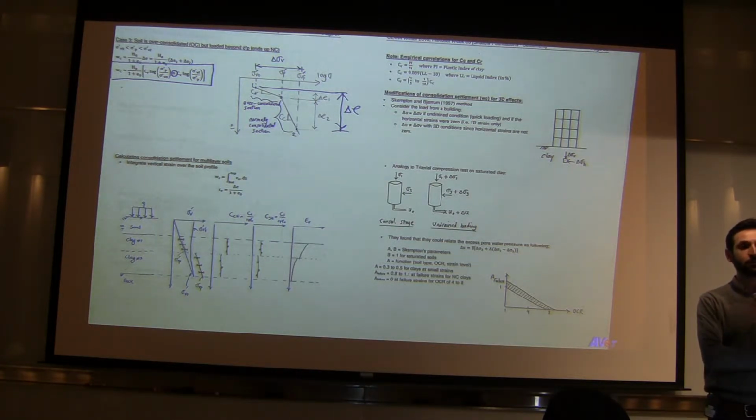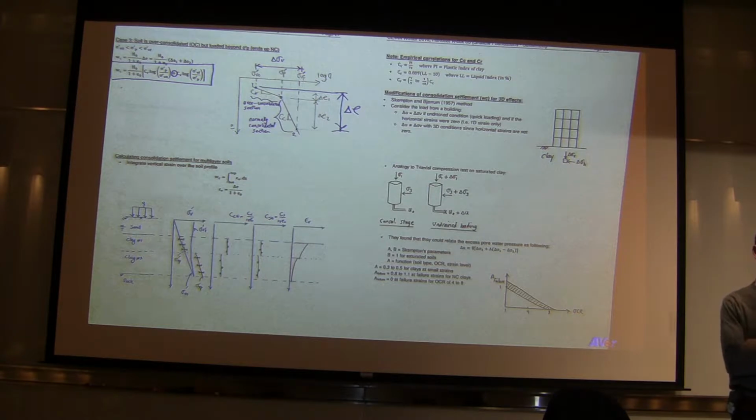So once you add those, because you don't want to drill alone, you always want to get samples and do lab tests on it. So it ends up being probably close to $10,000 for probably one or two borings with the tests.